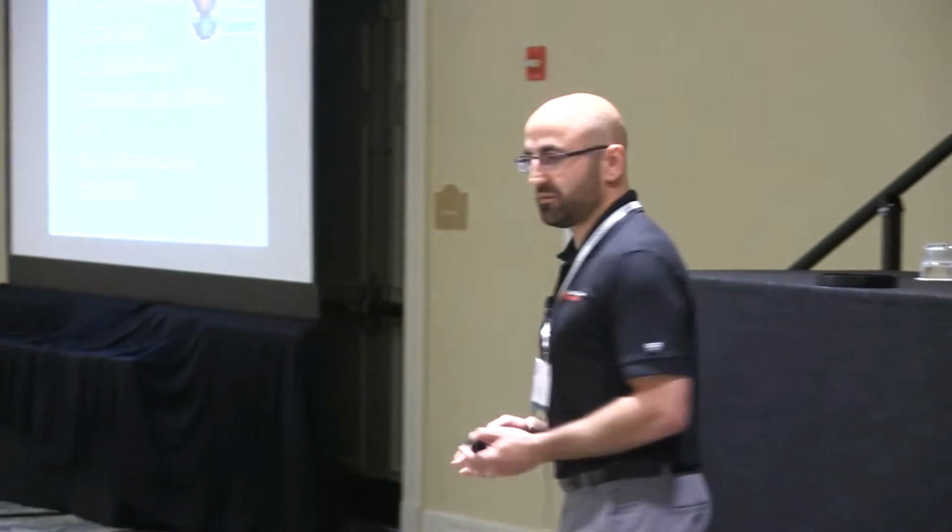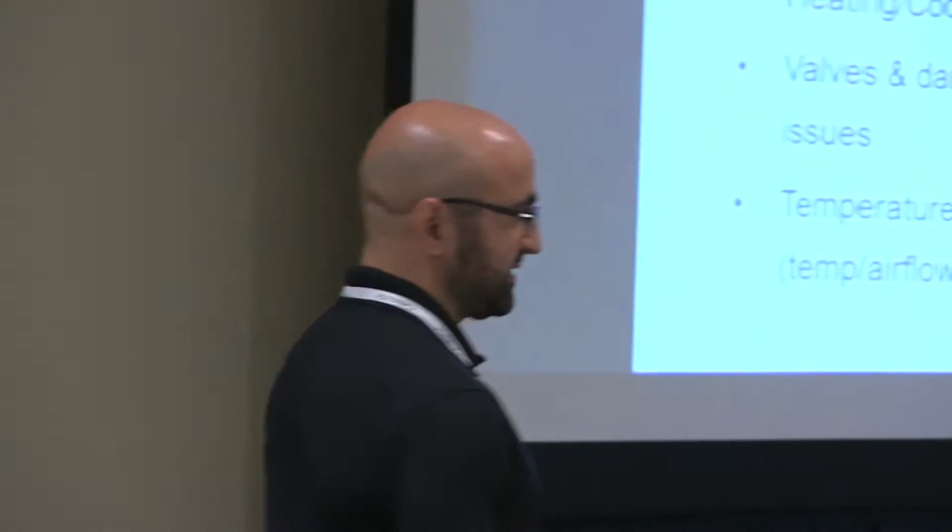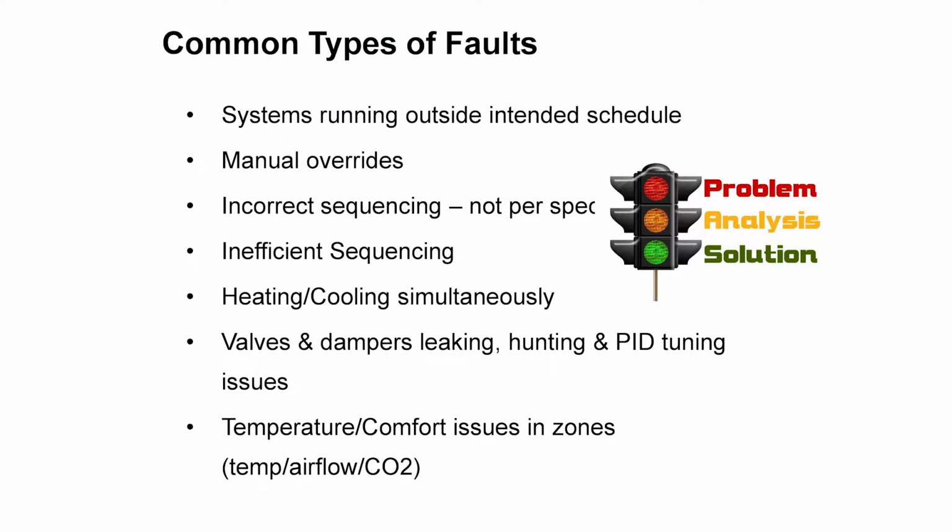So what are the kind of things that we're finding? We're not in the business of finding your chiller replacement or your lighting replacement, anything that we would classify as low-hanging fruit that you can easily find just in a walkthrough. We're finding the stuff that just takes too much human labor to find at scale in a building. And you might be able to find this stuff in a sample of building systems, either pulling trends off the BAS, deploying data loggers, walking through the building, looking at a BAS graphic. But at scale, it's just not possible, especially at the larger buildings, right?